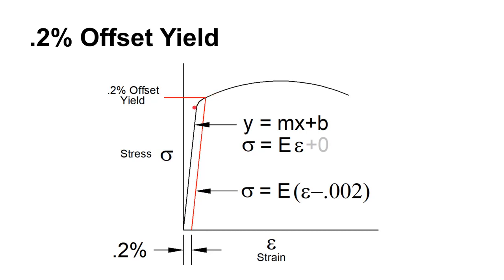We have to actually get points for all of this to measure this. But we find Young's modulus. That allows us to draw a line along here that will model and follow those data points in the elastic region. And then we offset that line with this strain line, which would follow this equation.